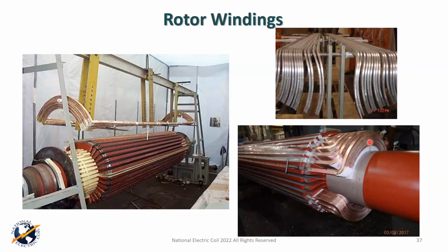Now, we talked about brazing a minute ago and the need for qualifications, and anybody can make a braze joint. Today, just to take advantage of modern day manufacturing, speed and cost, a lot of these edge bent coils with that joint, either some of the radial or some of the just conventional indirect cooled machines, have connections out at the end that are actually butt brazed.